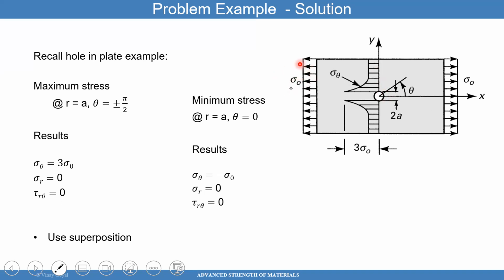is the negative of this load applied. So we can use superposition, because this plot or this configuration is for a load applied axially, and our situation is a multi-axial stress state where we know the loading in 2 different directions. In one direction it is PR over 2T, which is axial, and PR over T, which is hoop. So let's try to apply that concept.